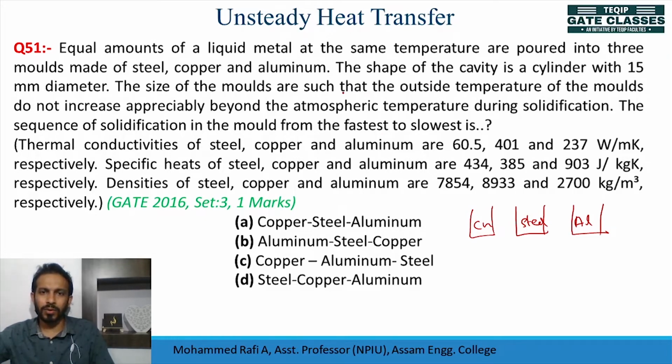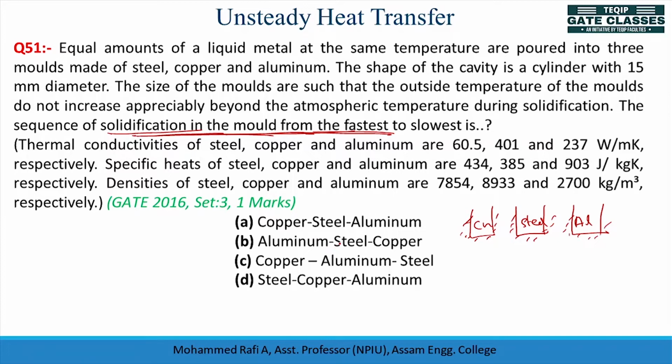The size of the molds are such that the outside temperature of the mold does not increase appreciably during the solidification. That means there is not much heat transfer outward. Whatever the mold material is, there will be some heat transfer. So here the question is about the sequence of solidification, meaning how fast the heat transfer is taking place. So it is a question related to the thermal diffusivity, right?